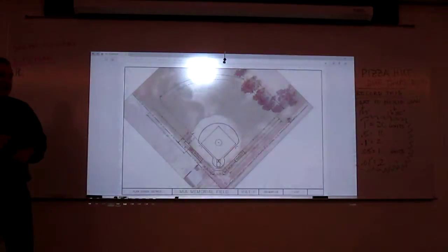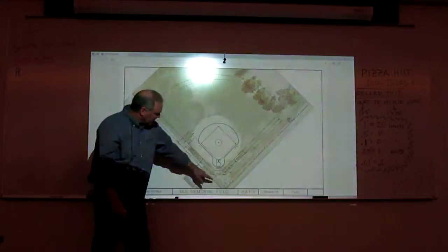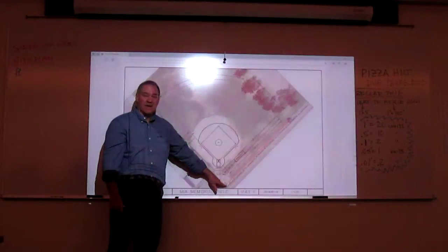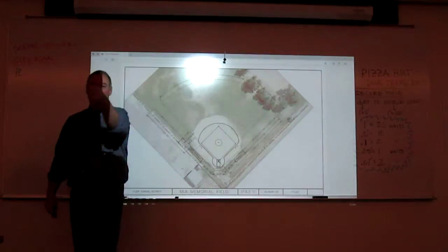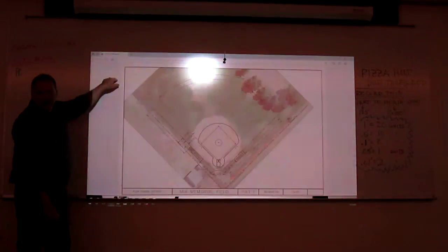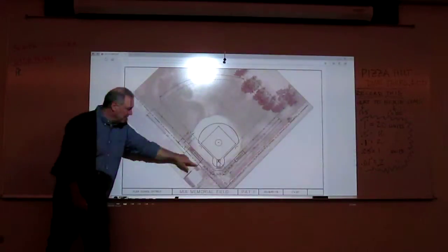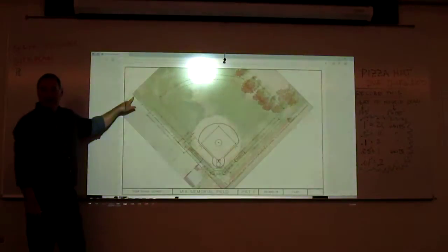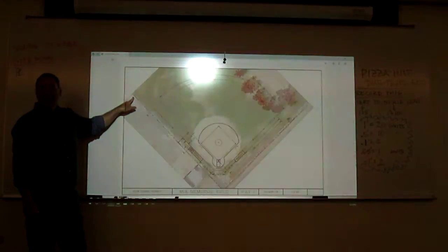But what we need to use for our property, because the shot you took in the corner is going to be almost perfectly accurate, because you were right inside of it. You were right on top of that piece of rebar. And then we'll use this point that's way back over here. That's going to give us a really good boundary here, one I feel really confident in. It'll be plus or minus a couple inches.